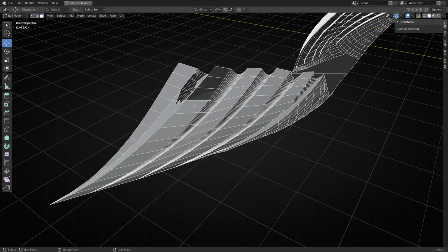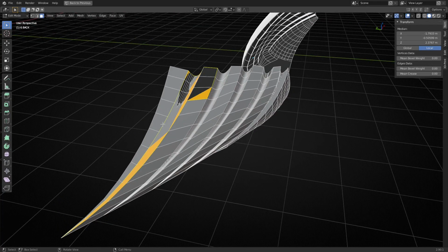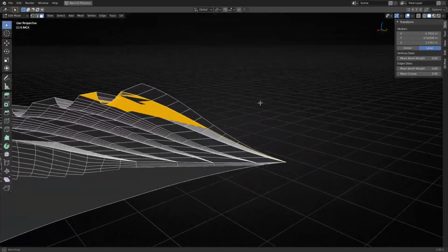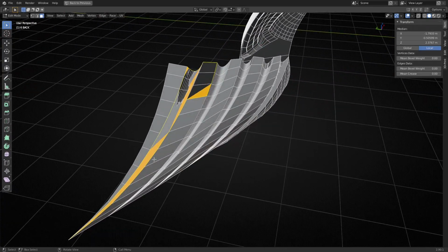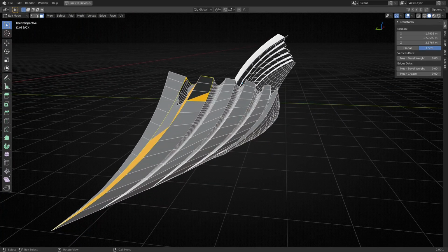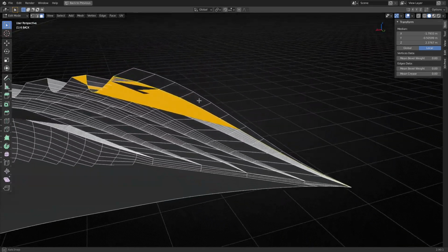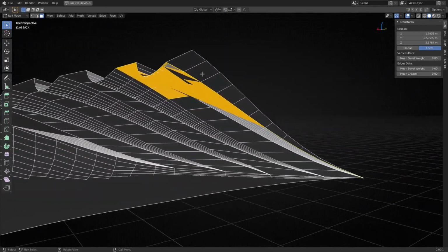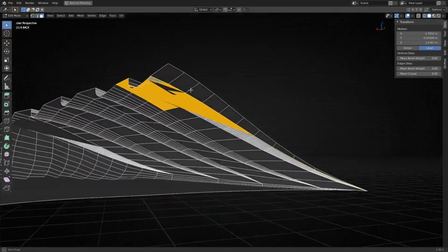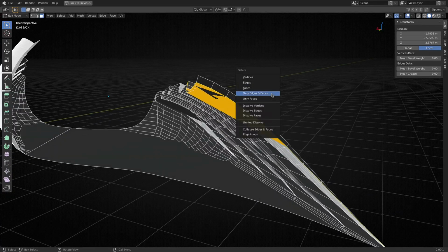Like these polygons, for example, this one is gray, but these ones are black. I just clicked here, and I see this weird long face selected here, this giant ngon that obviously shouldn't be here, right? It's just blocking this divot here, and in general, it's just an obvious mistake. Probably you just had some selection and pressed F by accident and made this ngon, or something else happened. Anyway, I just found it by accident, but I'll just delete it, right?